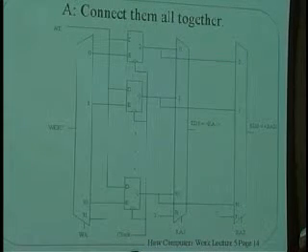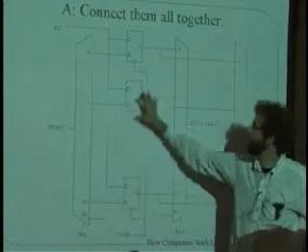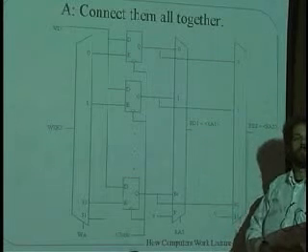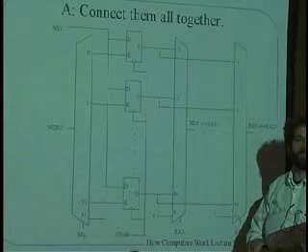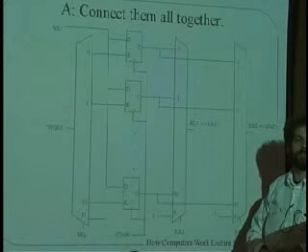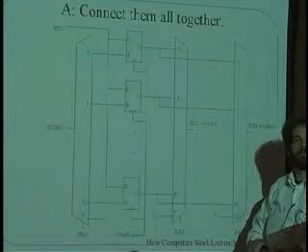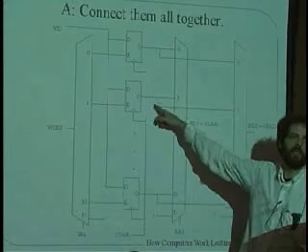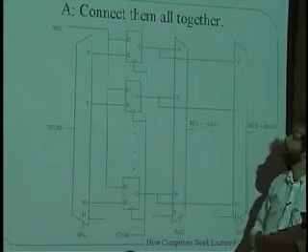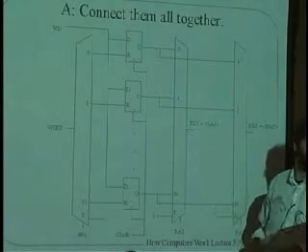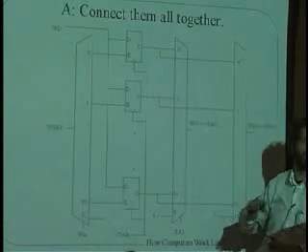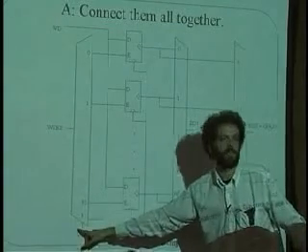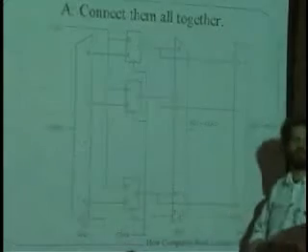It's really simple, okay? And each of these units is exactly the same kind of device we talked about in the last few classes, and the same sort of device that's going to be used to hold the contents of the PC, for instance. A simple 32-bit register. 32 wires come out of those. That's absolutely right, yeah. If I wanted to, I could mess this thing up by putting a slash here on each one of the wires and putting 32 on each one of them. But the truth is that this works no matter how many wires come out of each one. So the architecture is general. In our specific case, yes, you are right. All of the data paths are 32 bits wide. The address path is 5 bits wide, and everything else is 1 bit wide.